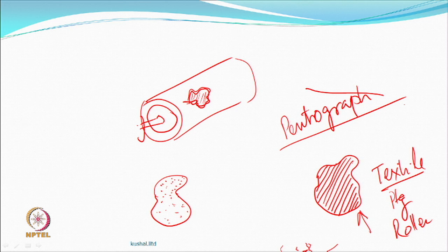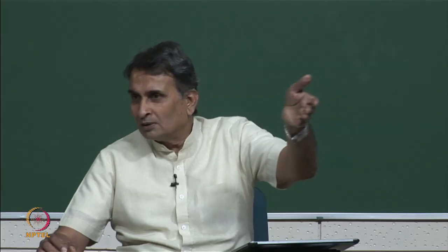So, when you have a roller over which there is a polymer coating, how do you etch the design? The design is on paper, somebody has made the design, let us say, and with this machine, one end is moved over the design, and the other arm gets moved automatically over the roller. So, there is a magnification or contraction.